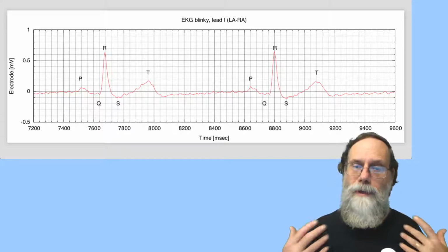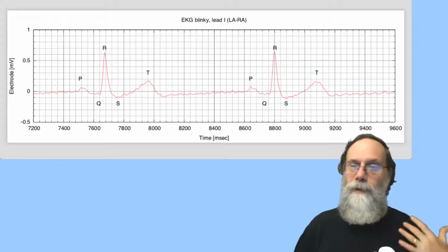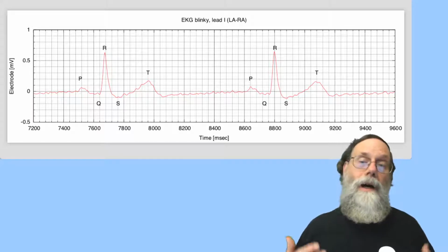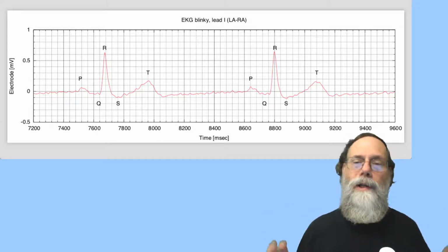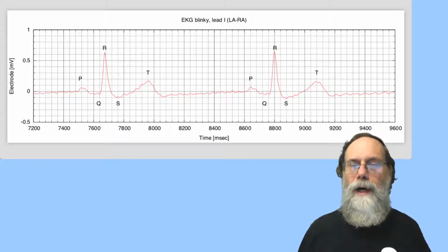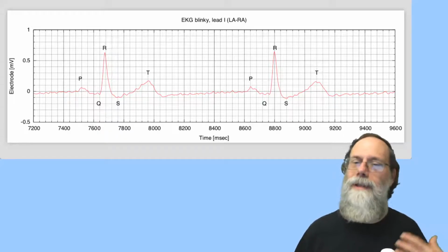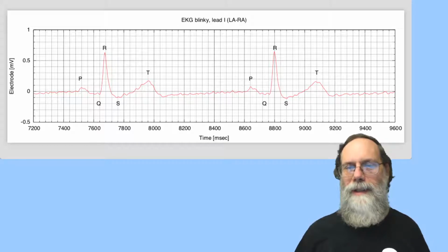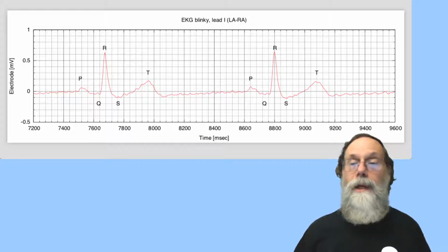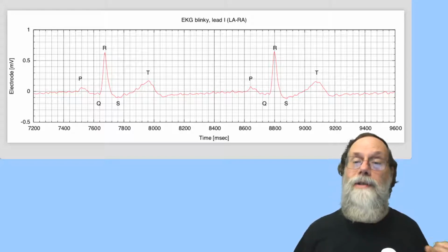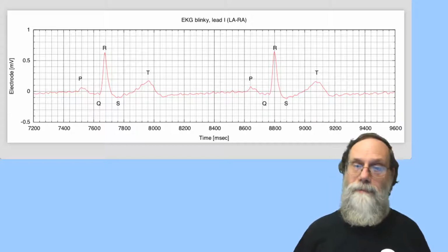Now, sometimes it can be difficult to do all the testing with real signals from the EKG leads. You only have a limited number of EKG electrodes, and they can be uncomfortable to wear, so you probably don't want to start using them until you've got something that you think has a good chance of working. So one of the things that's often done when data is expensive to collect, and in this case it's not extremely expensive, but still you might not want to be using the actual EKG for all your testing, is to build an emulator, to produce something that makes signals like the signals you're going to have, but are cheaper to produce.